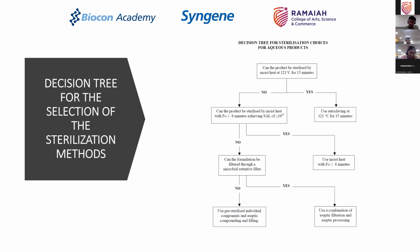In that situation, you have to use pre-sterilized individual components and aseptic compounding and filling, so that from the start till the end, every process step is sterile or aseptic. What this means is the way you charge your drug substance into the tank for compounding, the way you sterilize those compounding tanks, the way you transfer it from one tank to the other.